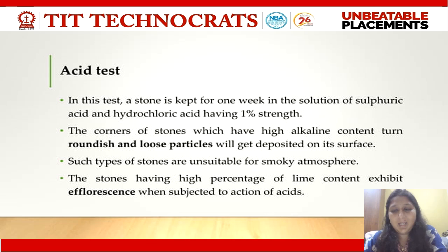Lastly, we'll be discussing the acid test. Acid test basically is to find out the amount of free lime or unburnt lime, or the lime content, in your stone. The more the lime content, the more the chances of efflorescence, and the less would be the strength. For this particular test, a stone is kept for 1 week in a solution of 1% sulfuric or hydrochloric acid. During these 7 days, the solution is stirred once a day.